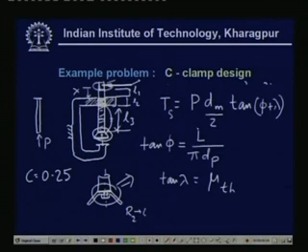So, we now know the individual values of T c and T s, and from this we can calculate the shear stress due to torsion. Now, let us come to a very, very important region, namely the region of engagement between the screw and the nut.